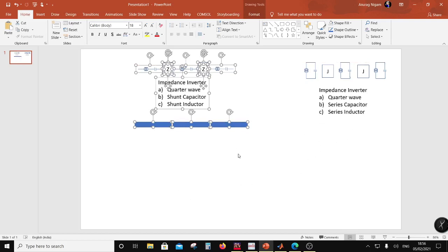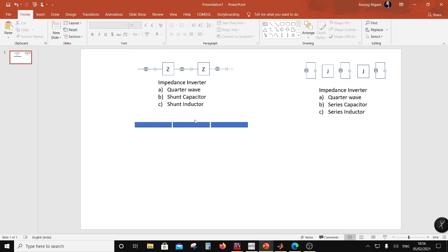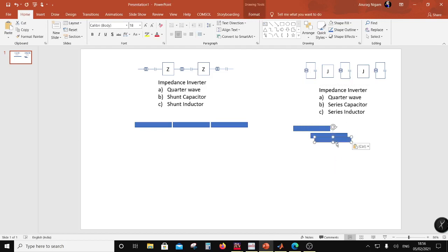require. So for example, the coupling can be this form of coupling, which is edge coupling, but it can also be a coupling which is a broadside coupling like this, for example, right? You can couple them like this, right? Okay, so this is called a broadside coupling. Again, this overall length is going to be lambda by 2, but then this overlap length is going to be lambda by 4, right? So, and then there can be coupling between them.